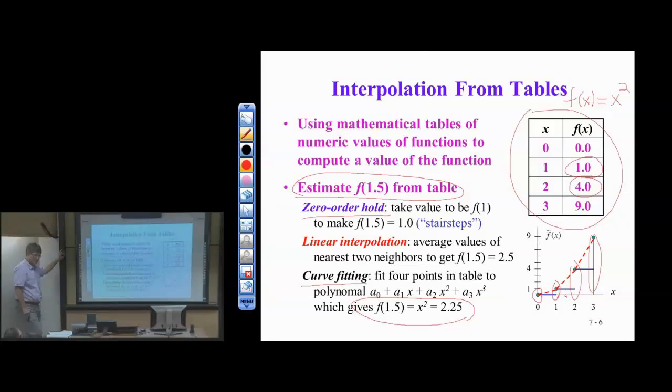Go ahead. Aren't sharper edges corresponding to more like high pass? Yeah, you get high frequency. So there are some high frequencies that get through, but it's 13.5 dB down from the pass band. So they do get de-emphasized or attenuated. They get through, but not at anywhere near the strength that the low frequencies get through. So the low pass effect is dominant.